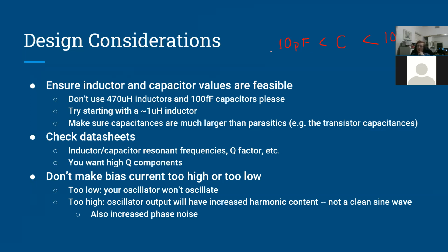And if you go below 10 picofarads, the stray inductance of your circuit, the parasitics, will overpower the actual capacitor you put in your circuit, and everything's going to be off. Like, you sneeze on it and your capacitance will change. So you don't want that.